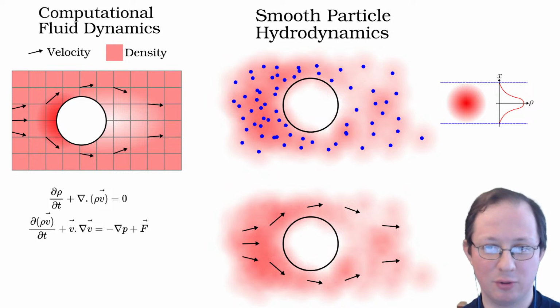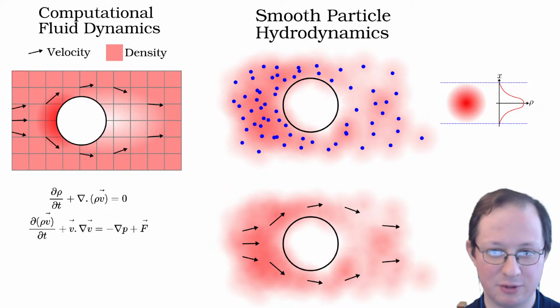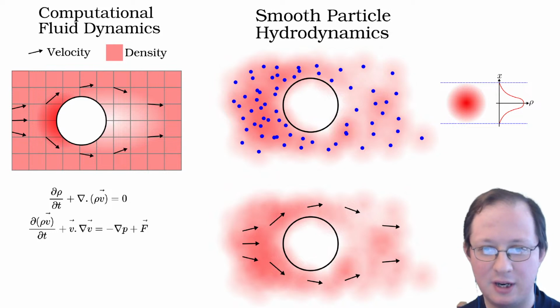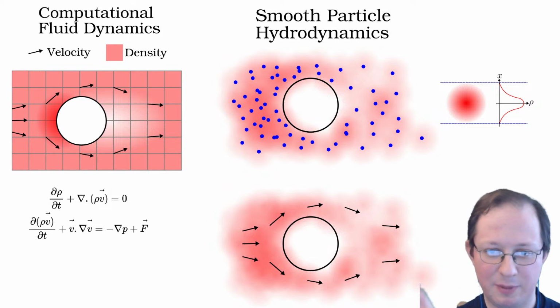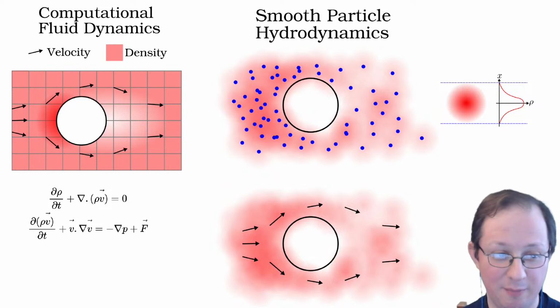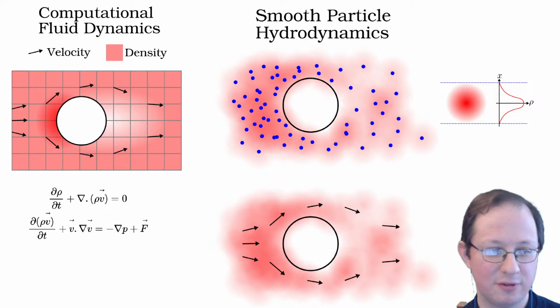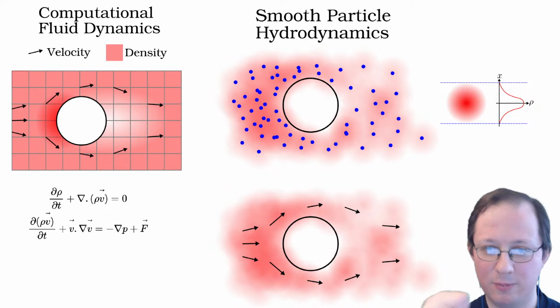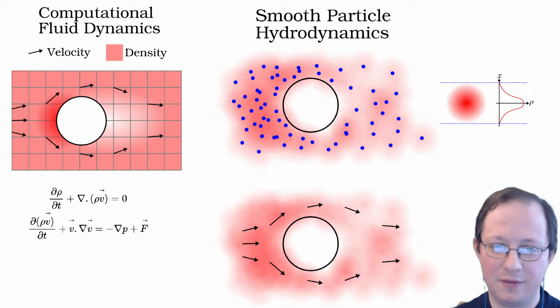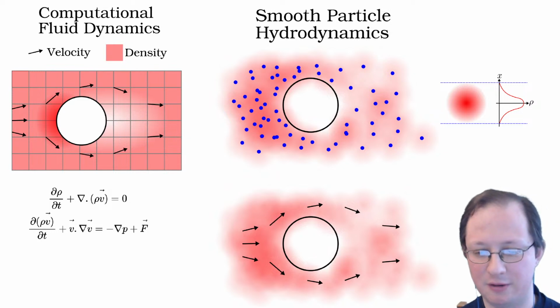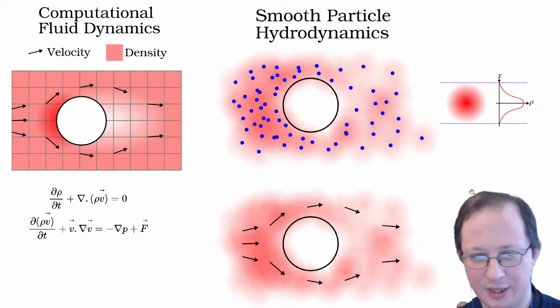You can have another approach called smoothed particle hydrodynamics. Rather than having a fluid that fills a volume, you treat the fluid as a bunch of tiny little ping pong balls, but they're not really ping pong balls that collide. They are soft, smoothed out ping pong balls. They don't have a perfect shell. They just feel a weak repulsive force among themselves. And so that's two ways.